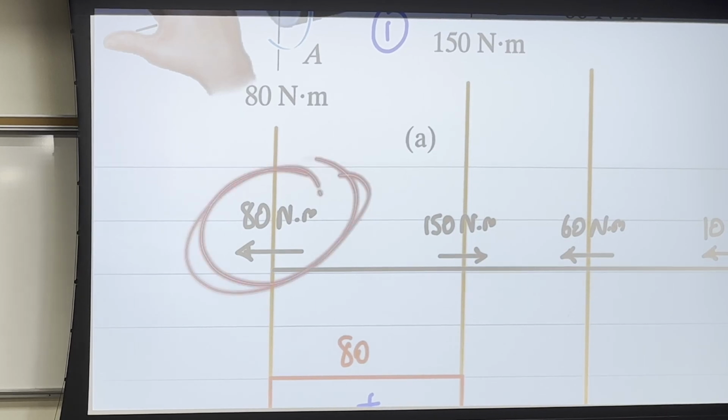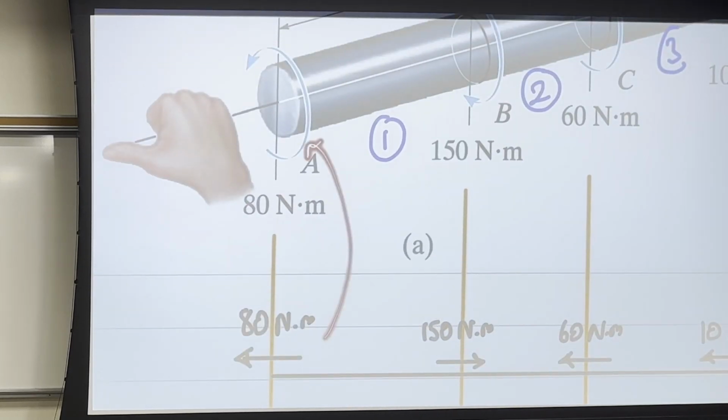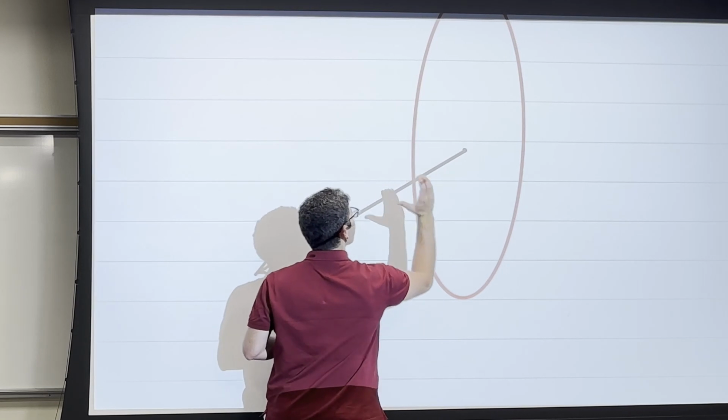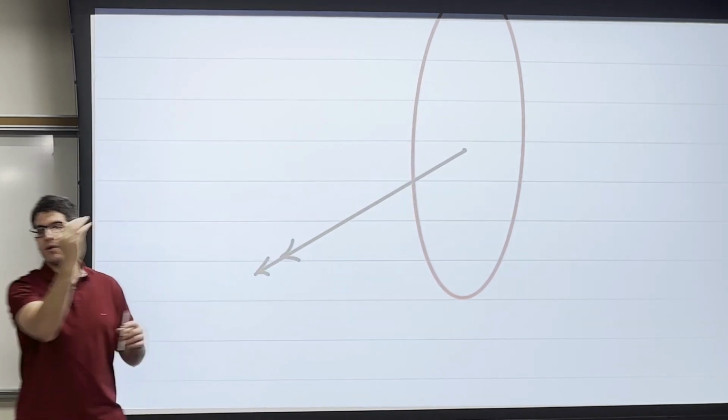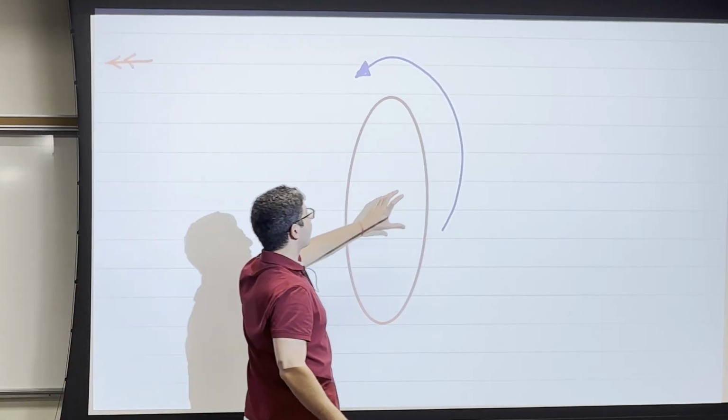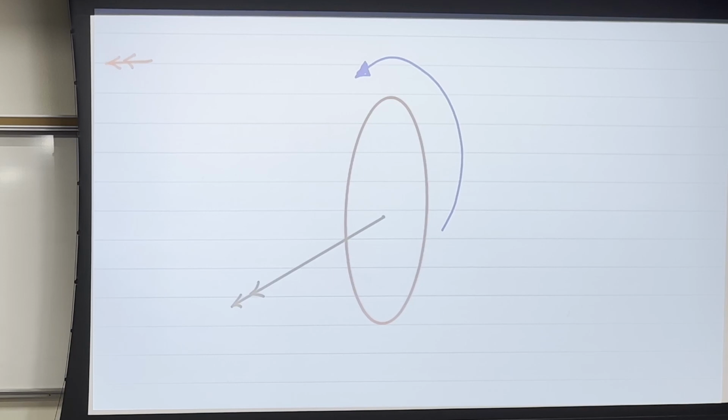Now, if I gave you this, can you transform it to this form or no? So now it's easy. My thumb will be pointing outside, so the arrow, I will put it this way, which is this side. Okay? Which tells you that, for example, this beam is gonna twist counterclockwise. So what can we benefit from this? We benefit from this: before applying torsion, I have point A pointing like this, and I'm gonna ask you, for example, what is the displacement of point A? So you know that A is gonna move counterclockwise,